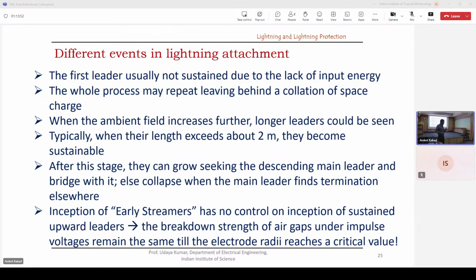In other words, these discharges, just because they are there in the first event, will not sustain. Why am I commenting on this? We'll come to know from the last line. This process is very common, very frequently observed in long air gap discharge in the laboratory, and we are sufficiently clear about the events, why it happens, why it's momentary, because of the balance between heat production and heat dissipation. Then, of course, every event produces some space charge, and this I'll skip.